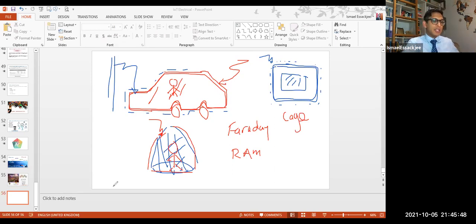And then ultimately, if it is longer distances, you will need to check for the voltage drop as well. If with the value you have chosen for the cable or wire it is going to have a voltage drop beyond the acceptable limit, you will need to go to the next size up, and then check the voltage drop again until it is within the acceptable range. Then you need to look at the protection as well. It is like 1.5 pages of calculation, or you have software for that, but the philosophy is around here.